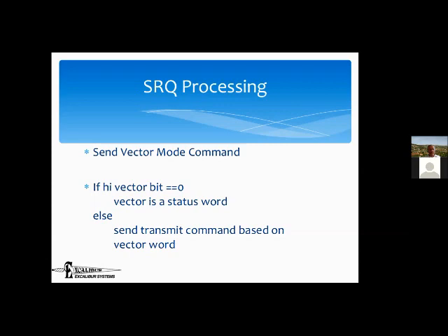So that, for example, let's say the engine is on fire. And there's a lot of data that the engine can send regarding this fire, and that data is all in subaddress 3. But subaddress 3 is something that the bus controller never asks for because he doesn't anticipate a fire. However, he does ask for subaddress 5, which is the fuel level. He asks for that periodically. He also periodically sends things to subaddress 2 to tell the engine to produce more thrust, or whatever it is that pilots want to tell engines.